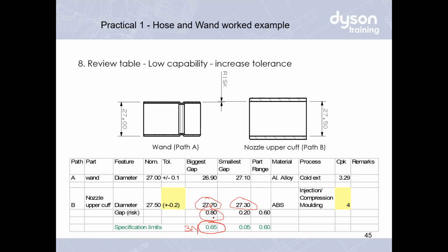If it's 0.8, then how? If 0.8, then I'm going to have a force that is less than 3 Newton, which doesn't meet my system design parameter. So what should I do? Then I go back to parameter design. Even though in robust design we say the steps are system design, parameter design, and tolerance design, in real life we start with system design, and we try to find a trade-off between tolerance and parameter in order to meet the specification.